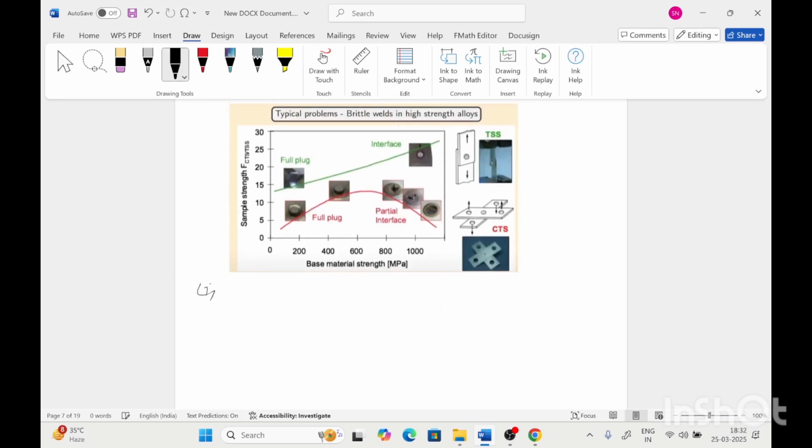The first problem can occur from the change in process window for small changes in composition, meaning a change in process window with chemical composition. If the chemical composition of the electrode or the welding material changes, then we have to optimize the current, welding time and the weld nugget diameter to obtain a good welding joint.